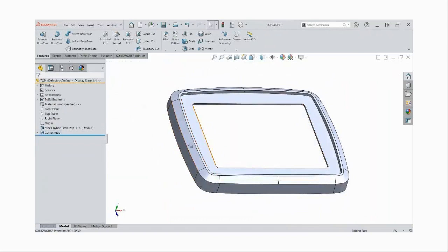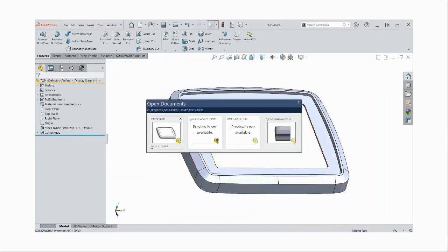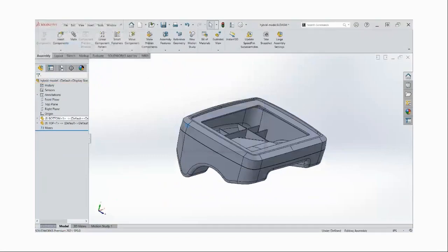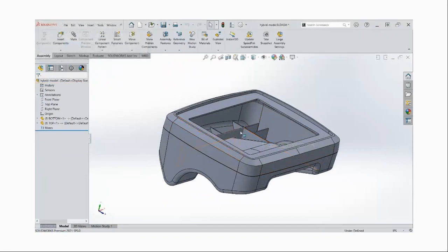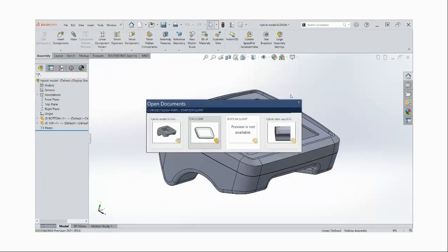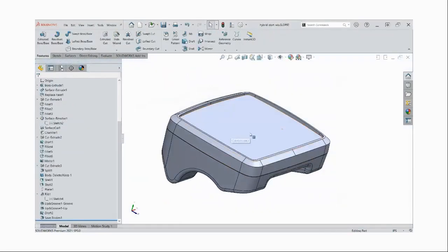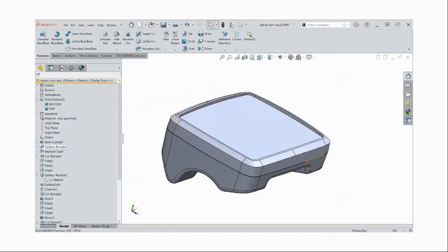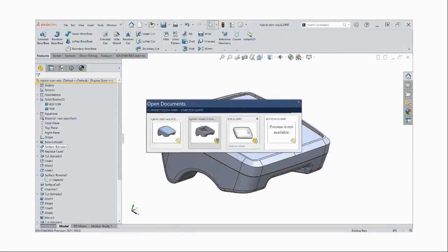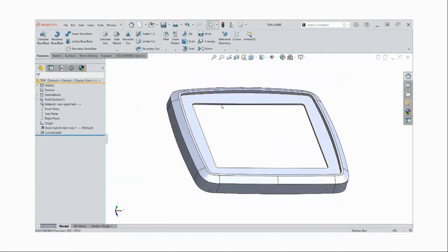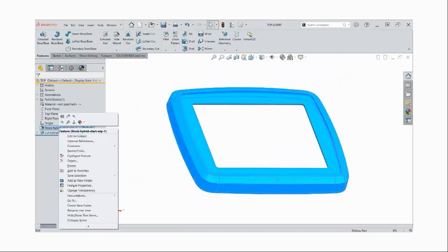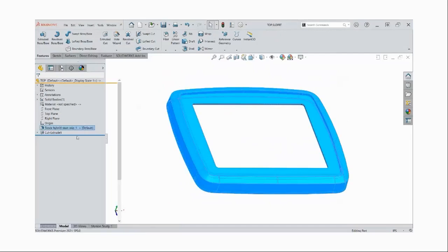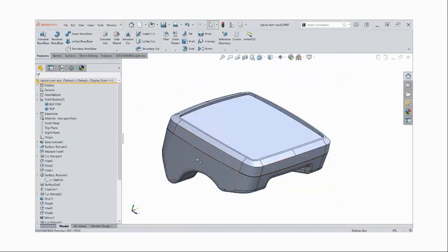Inside this stock model, build up additional features on top of this, and then I can end up having an assembly where we have those advanced features. We can insert the electronics and the other things we need into here. But when we ultimately come back to the original master model that we started with, we don't see any of those additional details, right? So when you're in one of these models where it's inheriting the stock, you have the option to right-click on it and edit it in context if you ever want to jump back to the full master model. It'll bounce you back there.